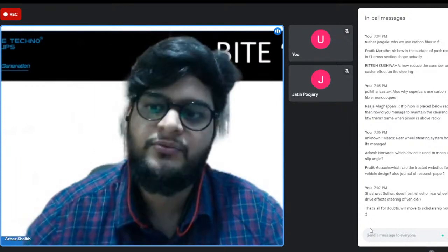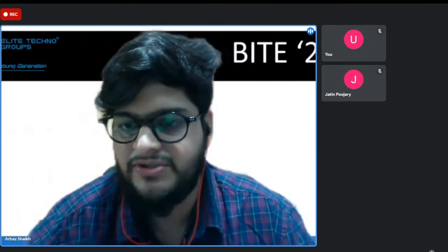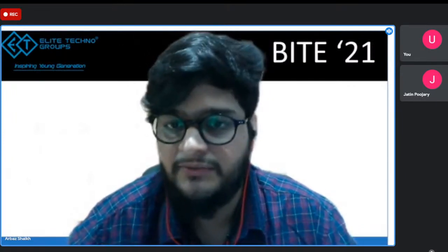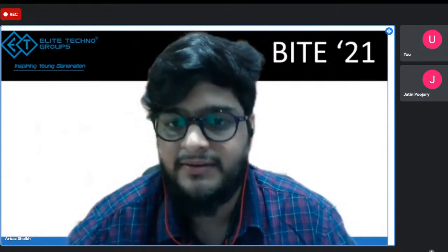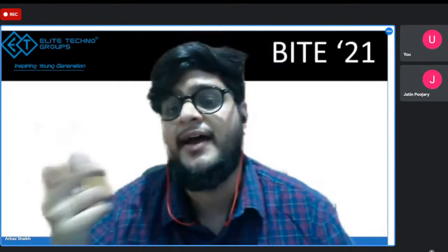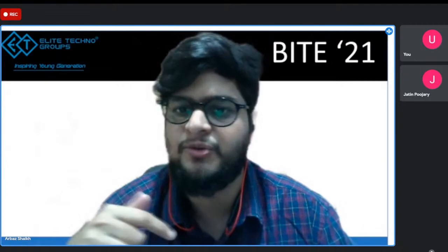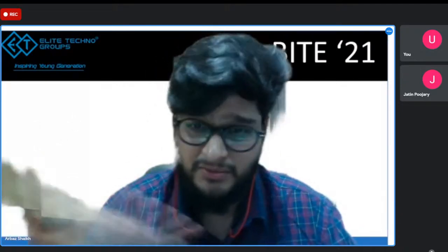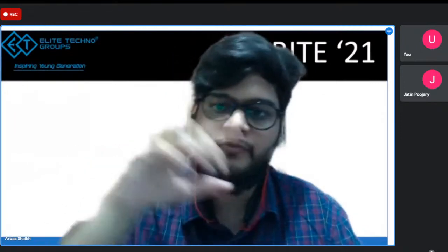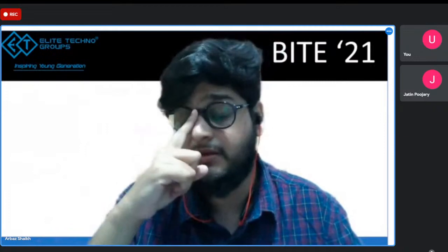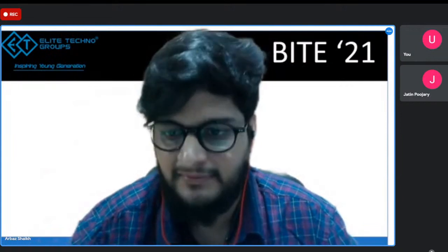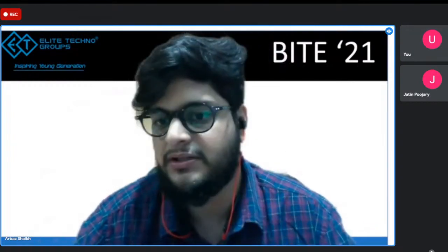Okay, Drupad is asking what assumptions we should make while considering the calculation for steering in a go-kart. Essentially, you'll start with your wheelbase and track width. Since you use a drop link mechanism, you'll directly go to the drop link, the tie rod, and your Ackerman arm, and then you can calculate with geometry instead of a rack. You directly connect your tie rod to the drop link, and whatever rotation is happening with your drop link will replicate the motion of your pinion, and instead of a rack, you will directly have your tie rods.